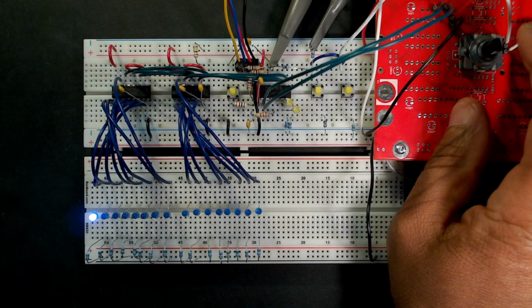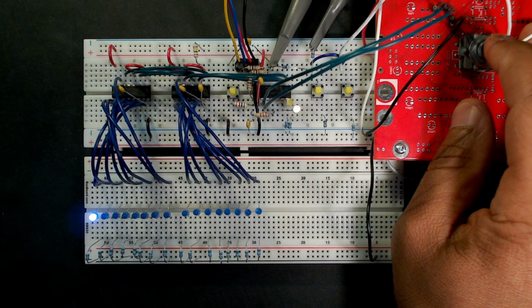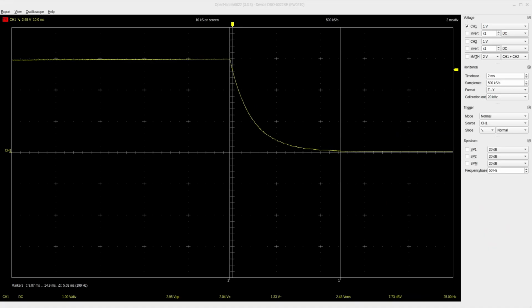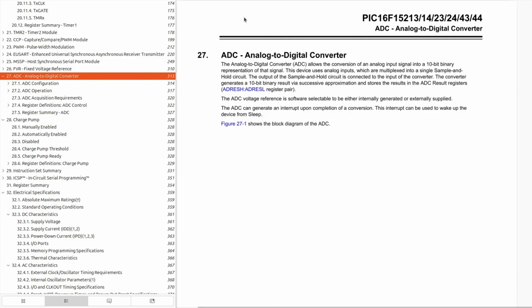And we can see when we push any one of those 3 buttons, the effect is exactly the same, even though the actual signal level is very different. The microcontroller doesn't know the difference because all 3 of those signals are below 0.2 VDD, so it thinks it's a 0. But as you might expect, this microcontroller does have the ability to tell the difference, and that's using the analog to digital converter.